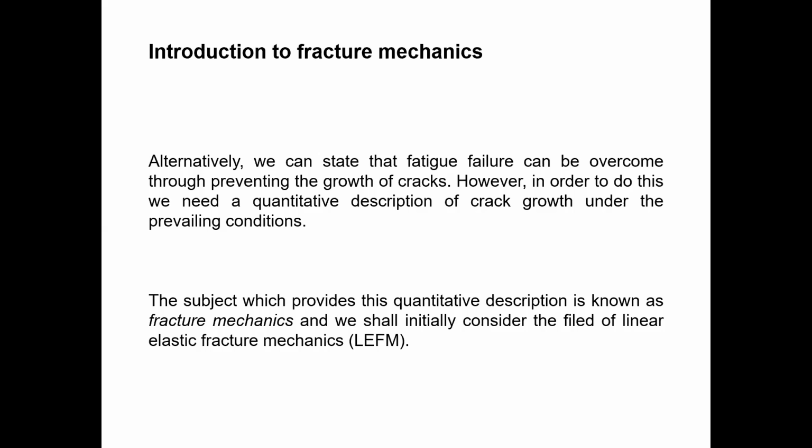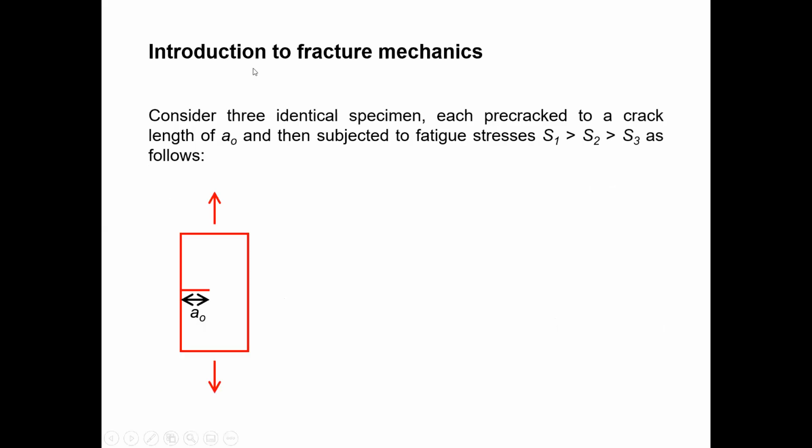I think you understand what I mean. With the Kf value, you don't know the behavior of the crack. You just know one single value. So rather than using that one single value, if you can further explain the crack growth behavior, that is a very good way to get the quantitative explanation. Okay. So you can see here the initial crack length, A naught. Here we explain how the crack length varies with the fatigue stress.